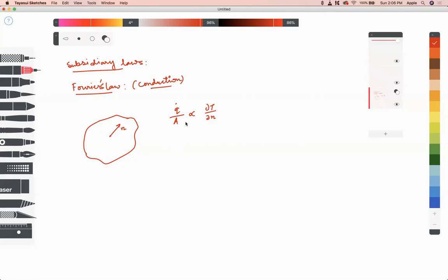So here you see you have your heat flux, which is the rate of heat transfer, in watts divided by meter square. And here your temperature gradient: delta T represents change in temperature, so this is in degree Celsius. You can also write it in Kelvin, not an issue, because when it comes to change in temperature, numerically both are equal. And the direction, any direction, if you measure the length, that is in meter, so degree Celsius per meter.